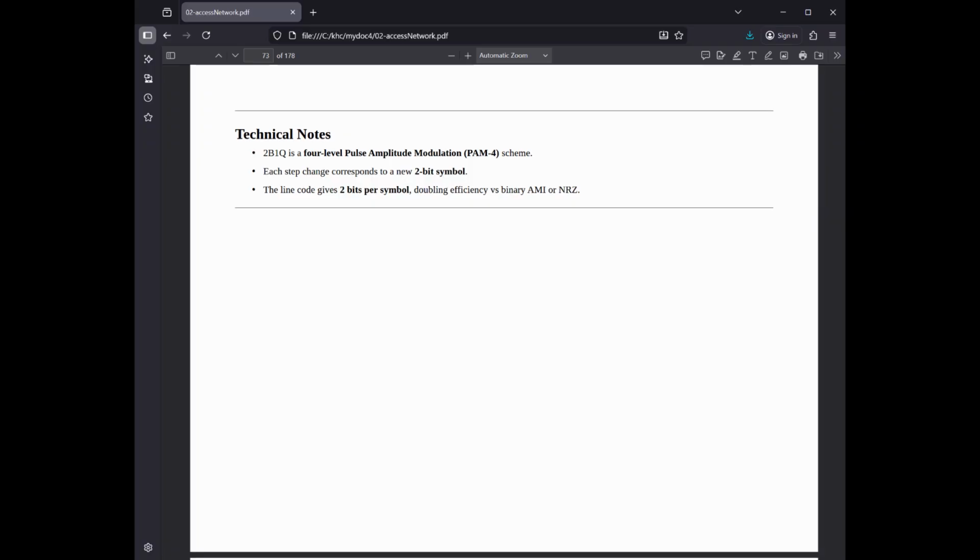Summary: the bad neighbor effect. Feature: high power in low frequencies. Why it's unfriendly: it causes heavy crosstalk into adjacent pairs. Feature: no notching. Why it's unfriendly: it cannot avoid specific frequencies used by other technologies, like AM radio. Feature: DC component. Why it's unfriendly: it wastes power and causes baseline wander, which stresses DC bias electronic components.